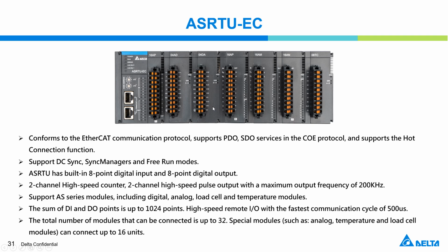Okay, for this module, you need to notice that the total number of modules that can be connected is up to 32, and for some special modules like analog, temperature, or load cell modules, you can connect up to 16 units.